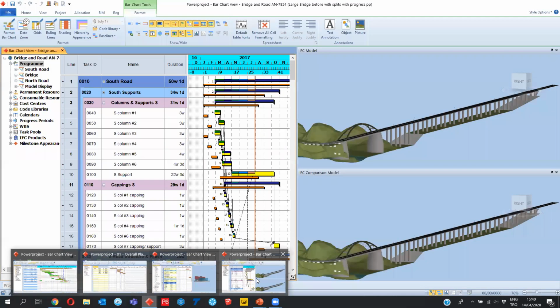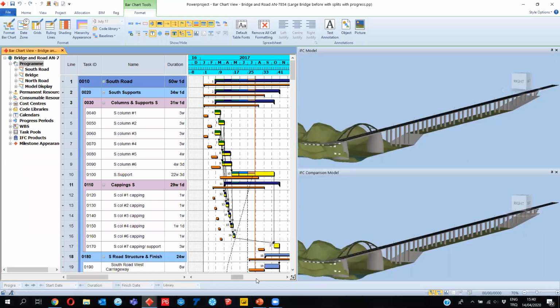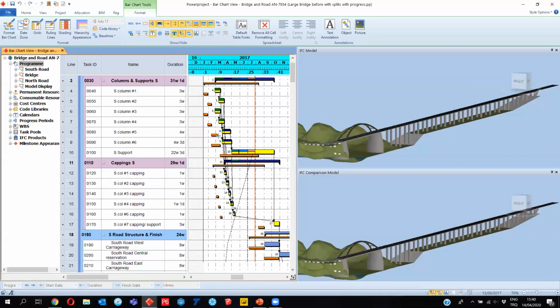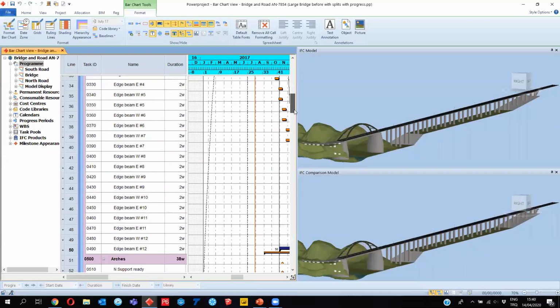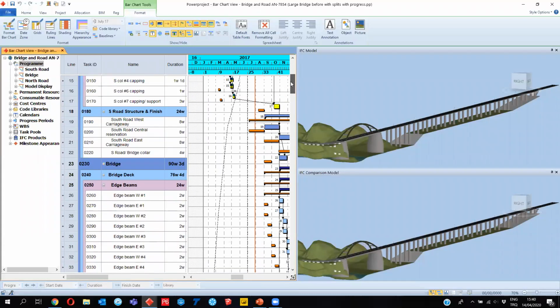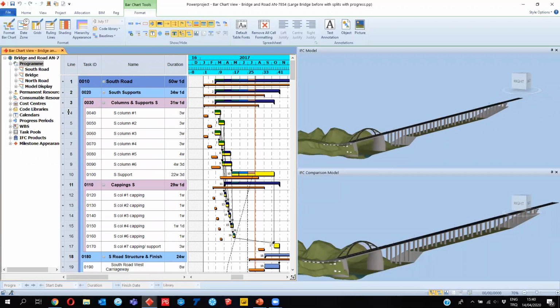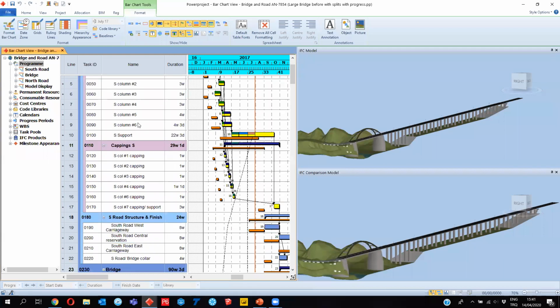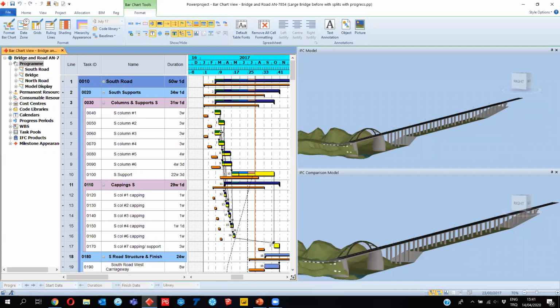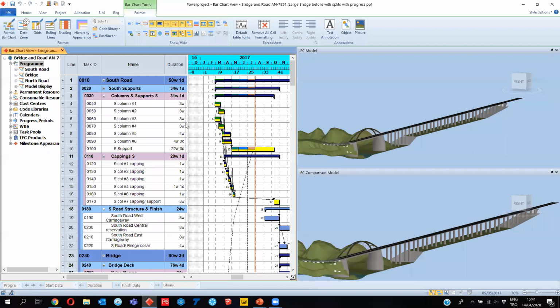The other thing is project control. So let's assume that we have a ready schedule. We also allocated all the elements in the 3D model with the activities. So you see here, I have activities, and also you see the baseline of the activities. Once I unclick the baseline in the format tab, you see the baseline coming out of the view.